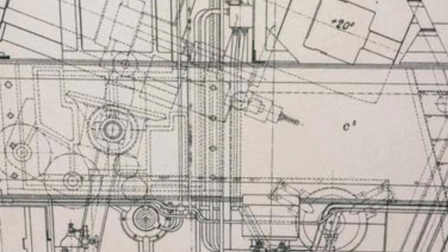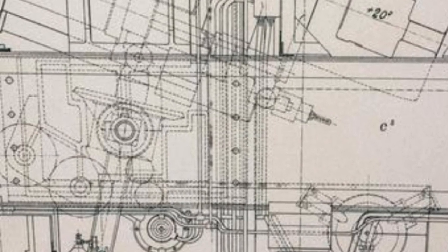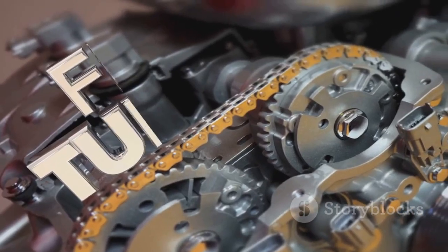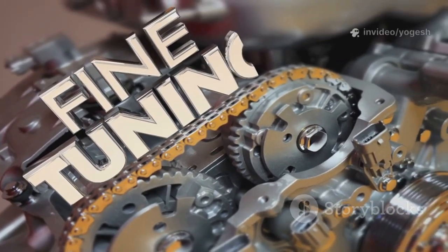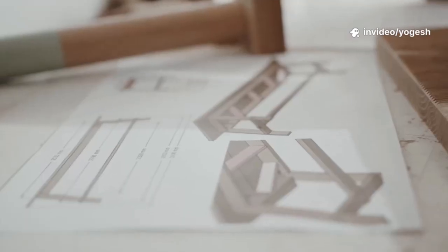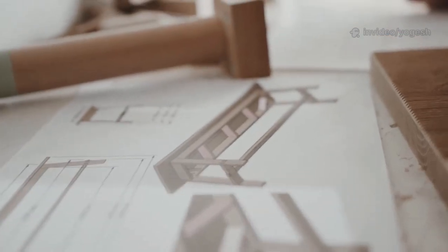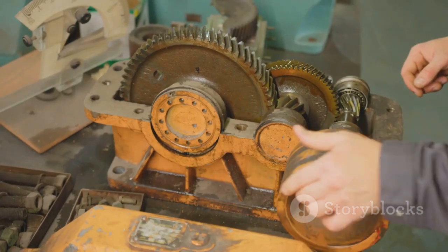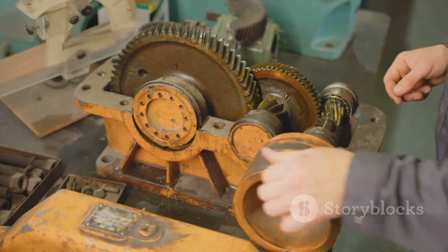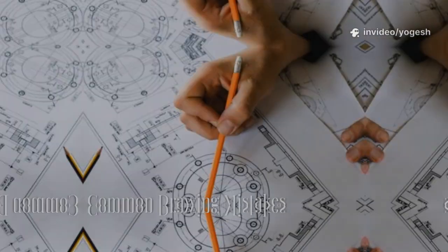Once parts are made, the assembly drawing takes over. An exploded isometric view shows the order and orientation of assembly. The bill of materials lists every part, with balloons linking each to its place in the drawing. An assembler can follow this single sheet to build the product correctly. This is engineering documentation in action.